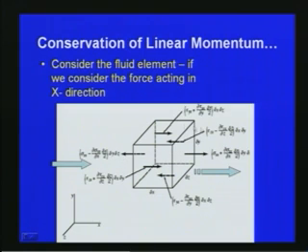And now we have also seen there will be surface forces with respect to the shear stress. So if the shearing stress is concerned, we can write on this face tau yx minus del tau yx by del y into delta y by 2, into delta x and delta z.